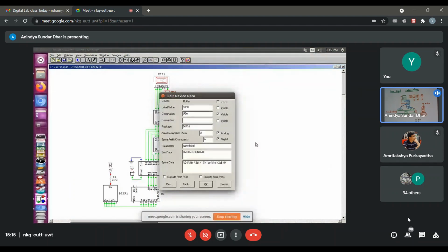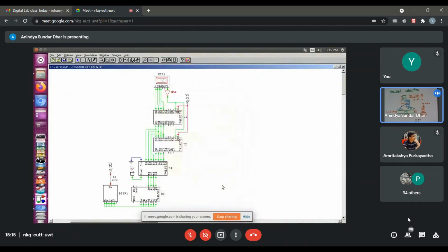So the propagation delay is not there, and the edge is actually coinciding with the settlement of the input. So the register is actually missing the value if I do not use this buffer. In reality, you may not really have to use this buffer, but at least in simulation I am doing so.